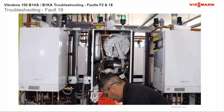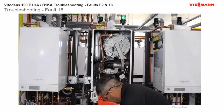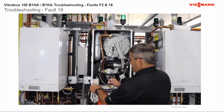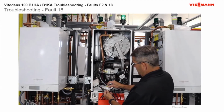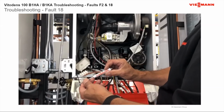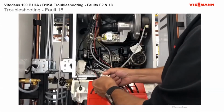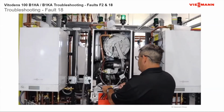So once we put our wires back together, put our new sensor on, and put our cover on, once we put the cover back onto the boiler, we're going to put our wires back on number 3 and 4 on our outdoor sensor location. Remember, small screwdriver. Make sure you always pull on your wires. Make sure you're tight. Just a little trick that I used to teach all my people.